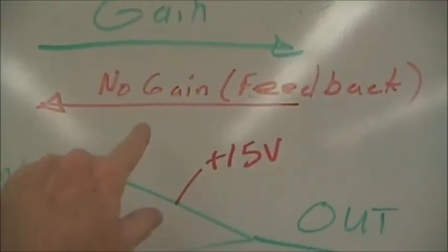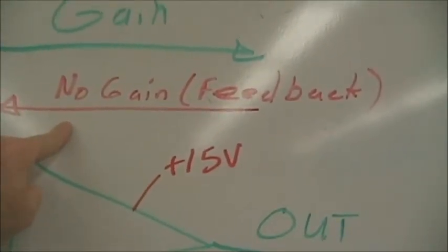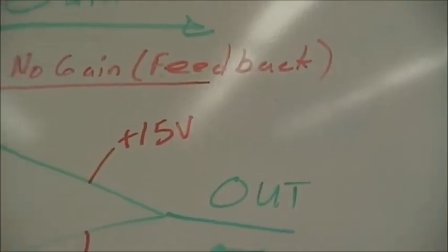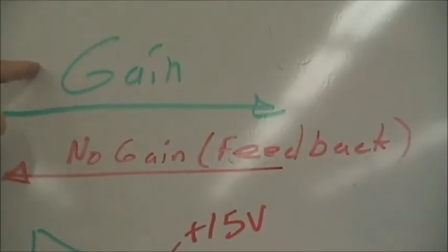Now, alternatively, we expect there to be no signal gain from the output to the input. That would be a feedback term, and amplifiers, we don't like to have feedback on the amplifiers. So we expect match for S11, we expect match for S22, we expect gain S21, and no signal or very little signal on S12. So let's see what we get.